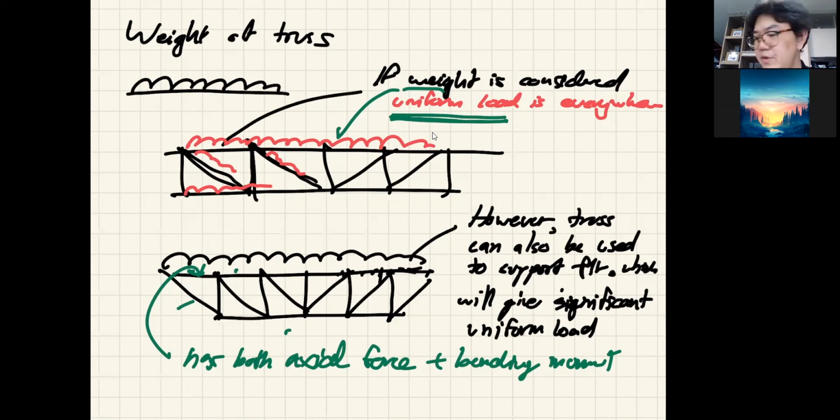But you need to take care of this in a very special way. Keep in mind that this member will have it bad because it will have both axial and bending moment, but it has the floor to help brace as well. So the unbraced length becomes 0, both under axial and under bending. So it's not bad.